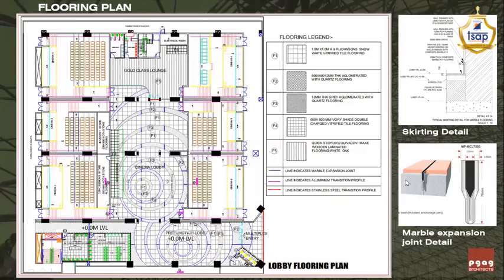You must have observed this while walking in a mall; you can observe all such small things. Like you will see this marble expansion joint in the mall itself, because most of the malls have composite marble flooring. Now this expansion joint you have already seen. Since there is a vitrified tile flooring in between the two marbles, the marble joint is not extended in the vitrified tile area. It is only limited to the area of marble flooring.